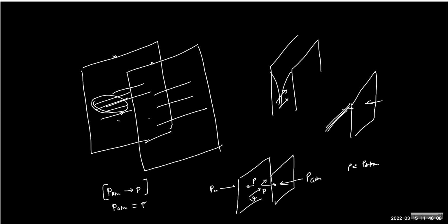Now we have the P and we have the velocity. This is how Bernoulli says that the sum of all types of pressure, static and kinetic, stays constant. So the motion of air is something like a kinetic pressure. Whenever the static reduces, some kinetic also comes into the picture. And the sum of the two, which we call stagnation pressure, remains the same as PATM.